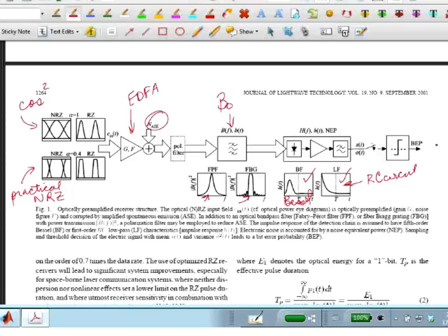It creates impairments, and we try to get DSP to help. But certainly to achieve what we call Nyquist packing of the frequency, to get frequencies as dense as possible, one way is to use pulse shaping. So the Nyquist discussion is relevant, especially in the coherent detection systems that we're looking at today.